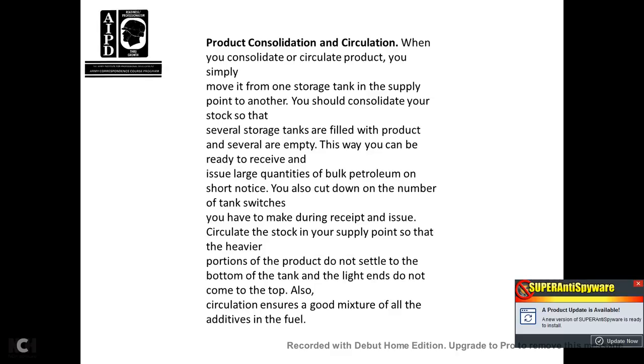Product consolidation and circulation. When you consolidate and circulate product, you simply move it into one storage tank at the supply point from another. You should consolidate your stock so that several storage tanks are filled with the product and several are empty. This way you can issue larger quantities of the bulk petroleum on short notice.